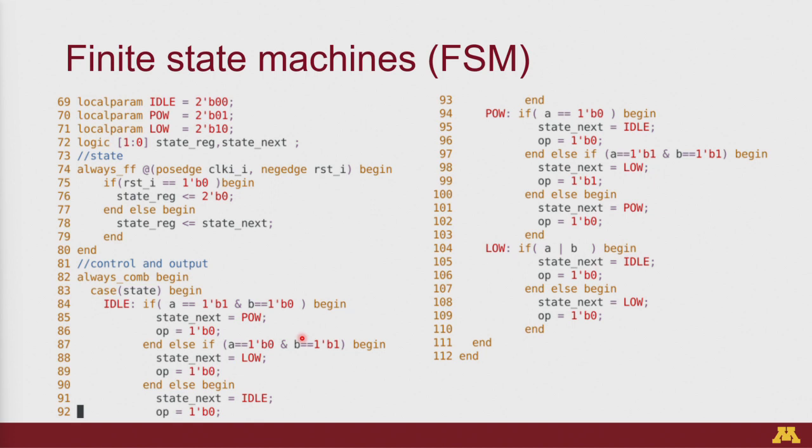Right? So maybe some things you want the designer on the top to say, oh, instead of 3 taps, let me have 5 taps. Right? But I don't want the designer to say change the states of my FSM, because the states of the FSM have to be these states only. If they change the states of the FSM, the whole design may break. Right? So that's kind of where the localparam versus parameter comes in.